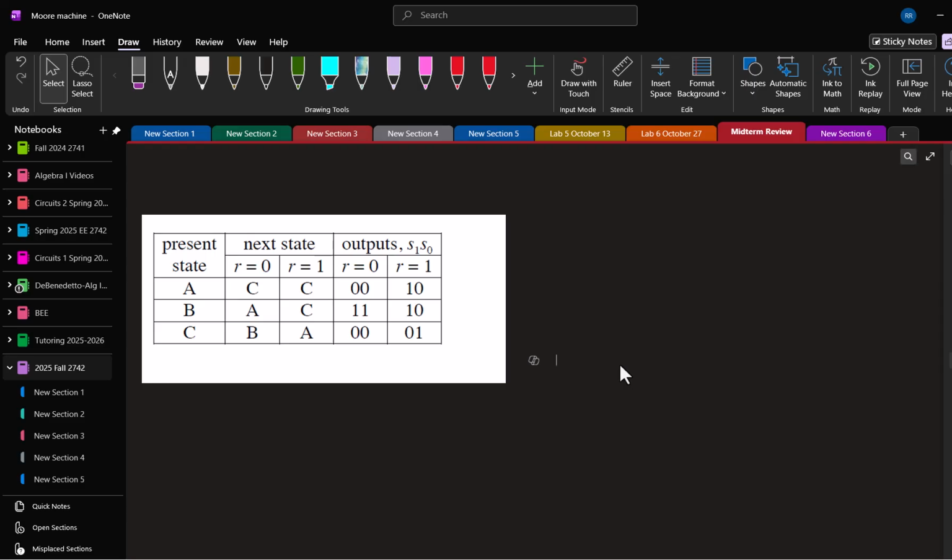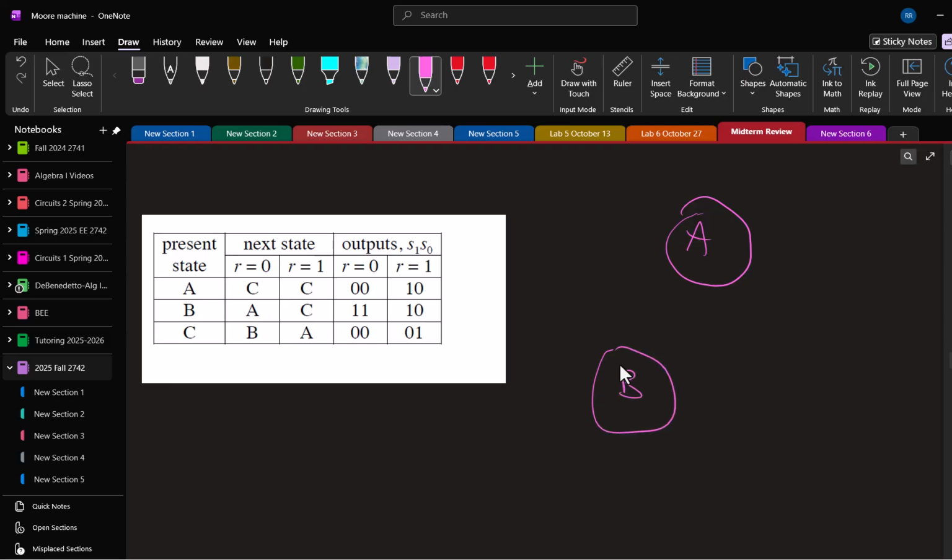A state table is useful if you have to do a circuit, if you have to actually draw out the flip-flops, but not if you only have to do Verilog. The only thing to keep in mind is whether or not you have to have a default, and you always should have one anyway, so it doesn't really matter.